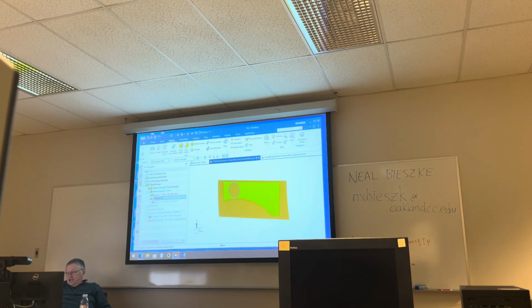I don't think the order really matters too much, but you go to this one, go to rename, and change the name. We don't want it to be called body side main slab, we want it to be called body side trim slab. Ultimately, we're not going to use it anymore, but we have to keep it, because our untrimmed slab is relying on it. So that's called body side trim slab.